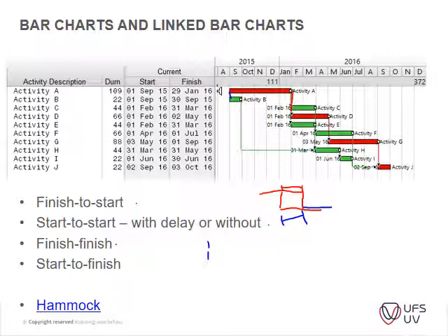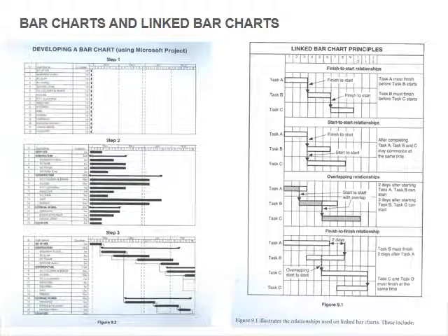So all just for noting for this stage, but it's worthwhile to note that whenever you do your scheduling, the most important thing from this chapter is your design methods, or developing your bar chart. You would list your items first, then schedule the time periods, and then link them accordingly. That is the main steps that you go through whenever you do your scheduling.